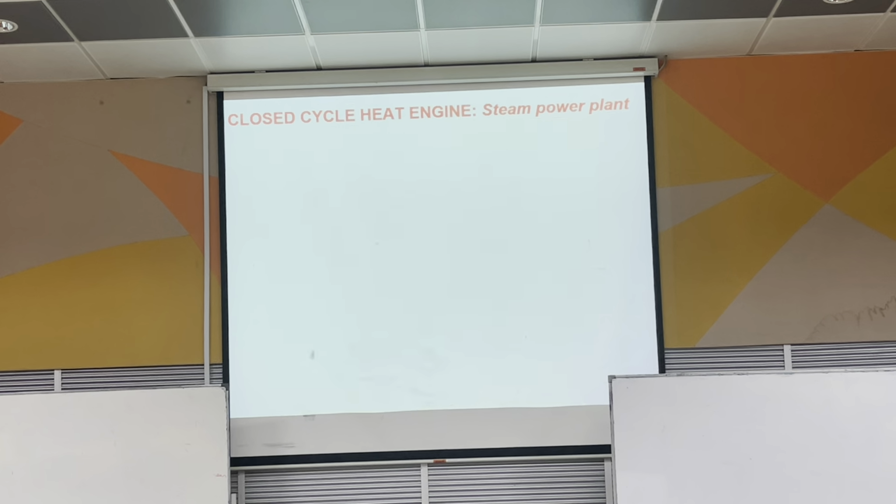So a portion of the work output of a heat engine is consumed internally to maintain continuous operation. Of course, initially when we started this whole thing, you still need some form of work to make this work first. But after that, the work in here actually comes from the turbine, which is why usually we just define this whole thing as work net out.